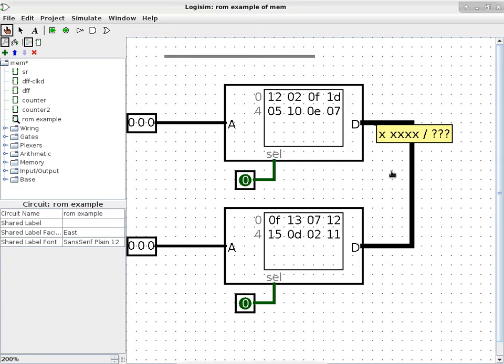So what this means is these wires, there are 5 individual wires within this bundle, and none is, quote unquote, being driven. What do you think that means? It's not being told to be on. Yeah, exactly. Nothing is specifying the content on those wires. Now, the reason nothing is specifying the content of those wires is because select is off. I'm telling the ROM, just be passive, don't do anything.